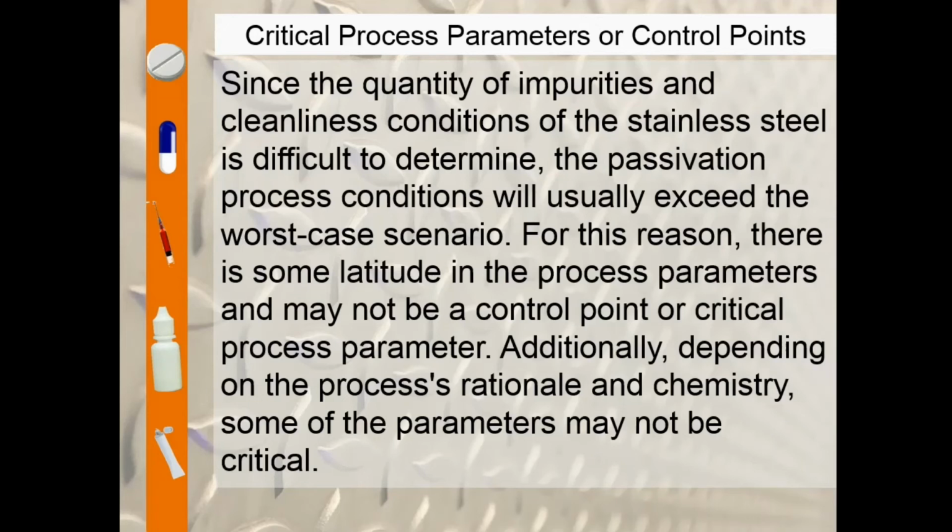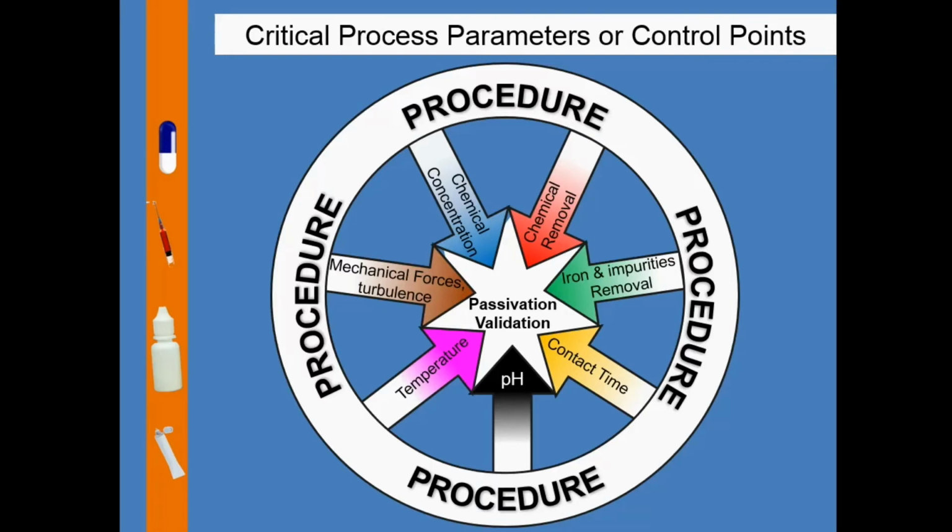There is no difference in these conditions if the solution is 2.9 or 3.1% or if we recirculate for only 28 minutes or 40. On the other hand, the testing method sensitivity is critical to proving that we remove the biofilm. Now that we have understood that some latitude is acceptable in some parameters, let's see the critical points in passivation by recirculation.